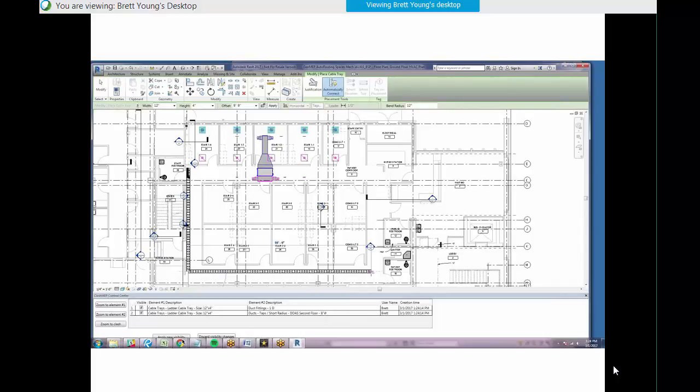I think when it comes to clearing the clashes, one of the things that sometimes is missing is a way to establish what is the right sequence of construction that is going to enable that to work. Something could be clash-free, but not constructible at all because the different detailers are not going to know how to put it together.